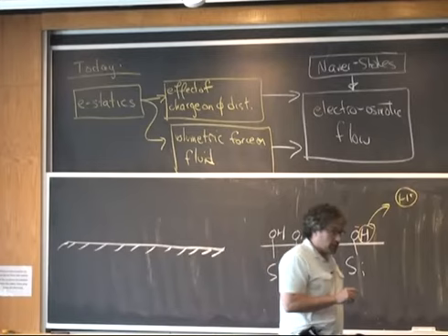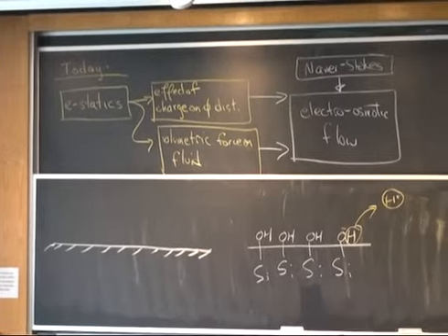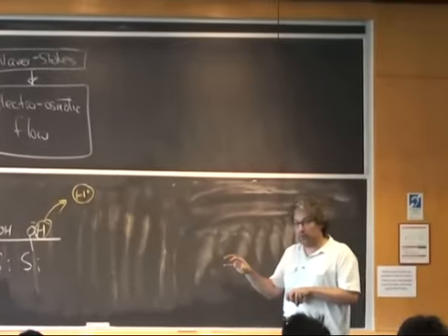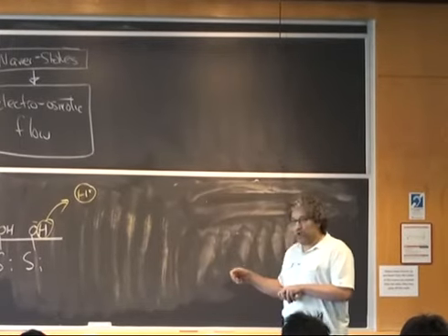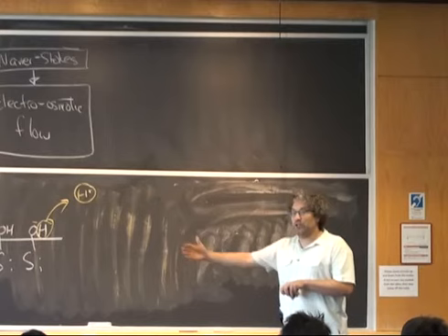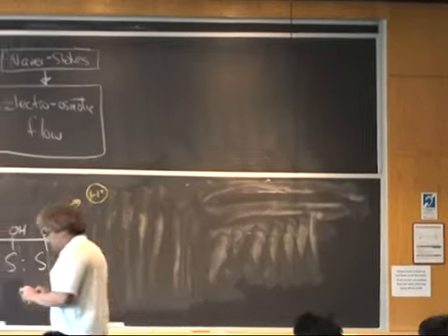So this is going to motivate us to analyze the system in a specific way. We're going to assume that the wall has a different potential. We're going to perform an integral boundary layer analysis of the flow near this wall. And the reason why we think we can do an integral boundary layer analysis is because all the action in this flow is so close to the wall. It's within 10 nanometers. I can just go 20, 30 nanometers away, and that's far enough for me to have integrated everything interesting. So I'm going to take a wall.